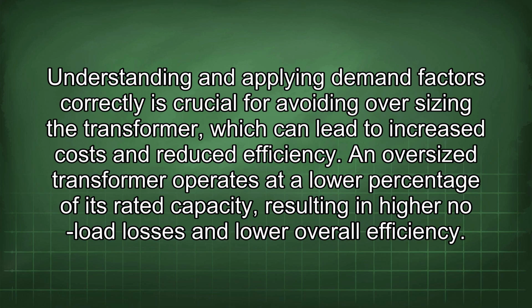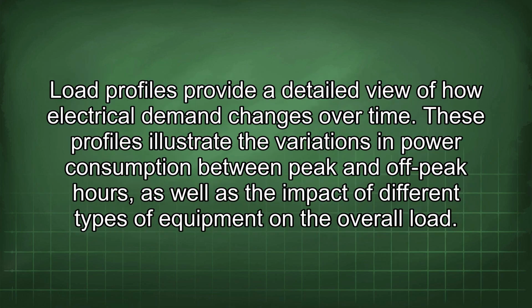Understanding and applying demand factors correctly is crucial for avoiding oversizing the transformer, which can lead to increased costs and reduced efficiency. An oversized transformer operates at a lower percentage of its rated capacity, resulting in higher no-load losses and lower overall efficiency. Load profiles provide a detailed view of how electrical demand changes over time.